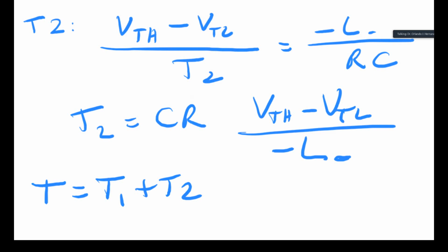And you can start refining from that. You can make the value of the components adjustable, so you can change it and maybe amplify and change the levels, and also add some digital logic to dump the charge and maybe get sawtooth type waveforms, and all of a sudden you got a full-blown function generator like what you're used to using in your lab. Okay, so that concludes chapter 15.